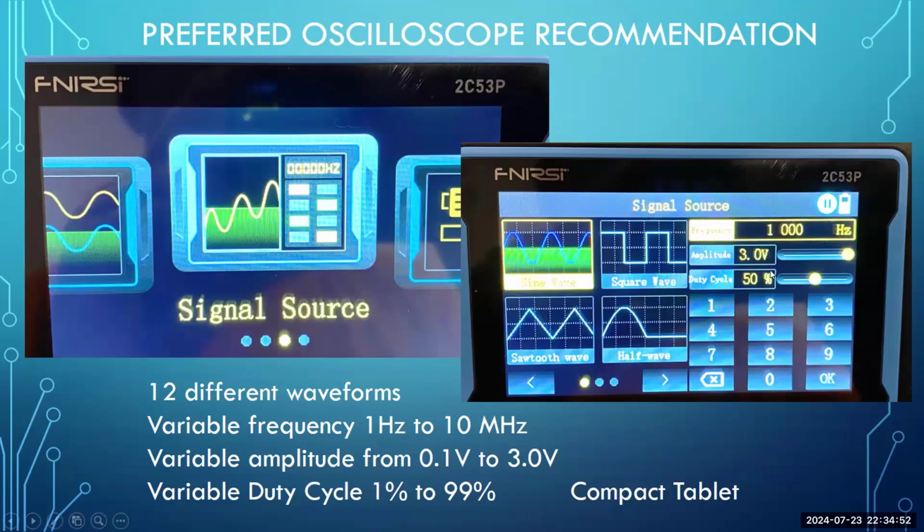You can do this. And duty cycle we haven't talked about yet, wasn't relevant in the previous illustrations because I didn't show you a square wave. But duty cycle is what percentage is the positive portion of the waveform to the negative. And we've had this at 50%. In other words, the positive portion and the negative portion were exactly equal to each other in terms of time. So that's duty cycle. So it's a very easy display for you to exercise.